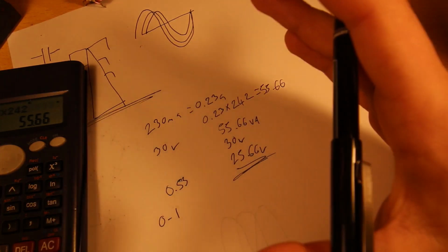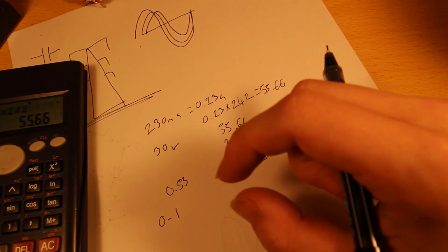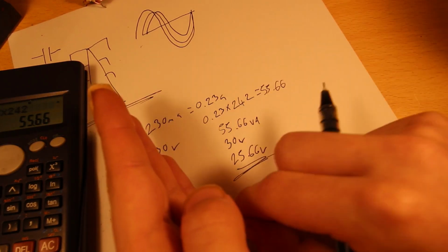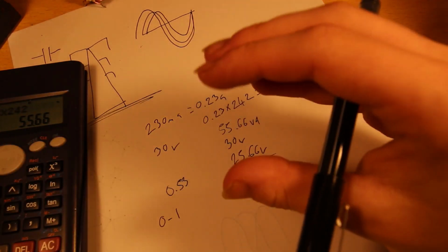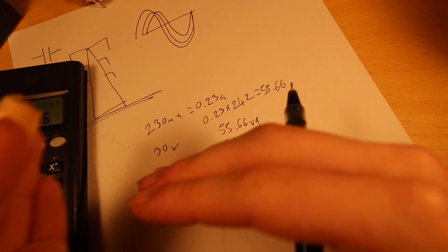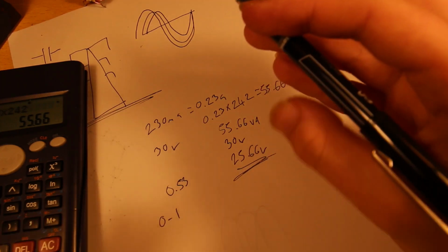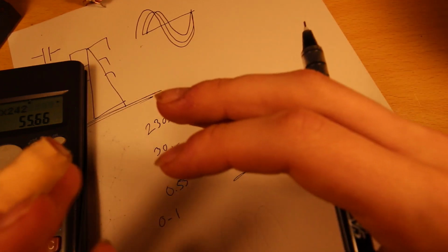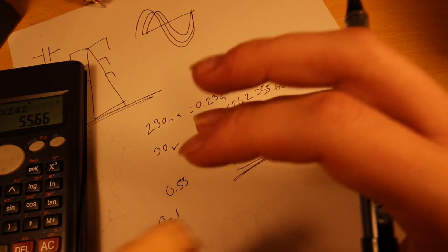You can see an example of cable capacitance actually in part 1, where I showed the IR meter, the insulation resistance meter, and you saw the current bump when I pressed the button. That was from the capacitive effects of the cable charging up, so it drew more current while it charged the capacitor, and then that went away when the voltage rose up. But these effects of the capacitive draws and the inductive losses and bad power factor loads, all of that combined causes substantial amounts of loss in the cables.